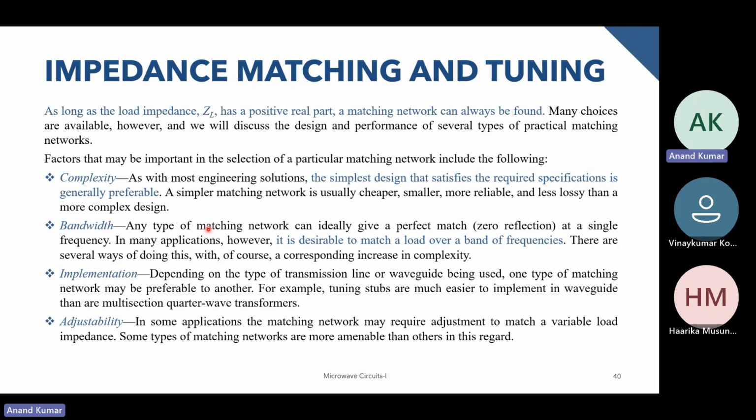Now, bandwidth is a real issue, actually. Impedance matching is very simple to do for a single frequency. But if you're working on an ultra wideband or a wideband circuit, bandwidth is an issue, and you actually have to do a lot of things to maximize bandwidth, and again that will come with a number of trade-offs.